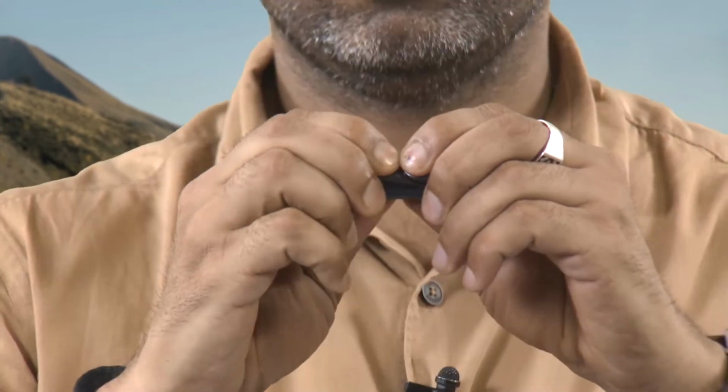Now, let us apply the load to the material, but change the rate at which I apply the load. I will apply a faster rate now to see how the material behaves when I am just pulling it. I am applying it at a very fast rate, and you see that when I apply this at a very fast rate, the sample fails before stretching to a specific length, or before stretching to a higher degree.